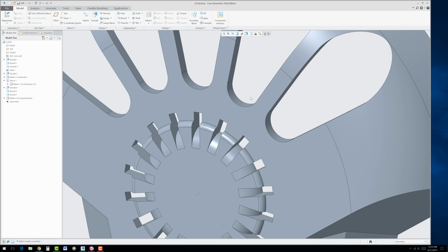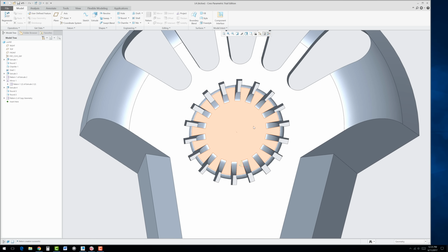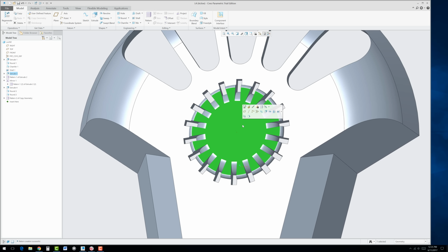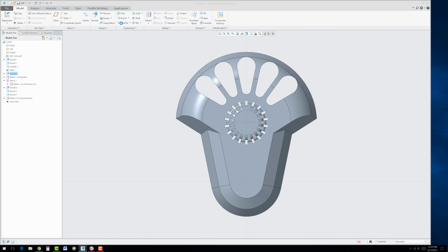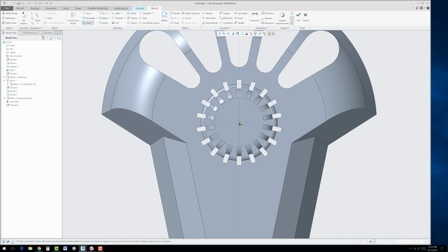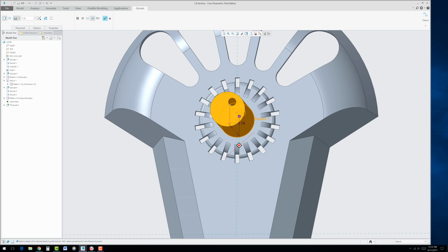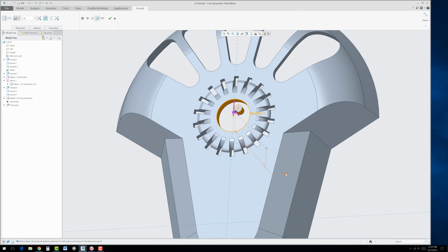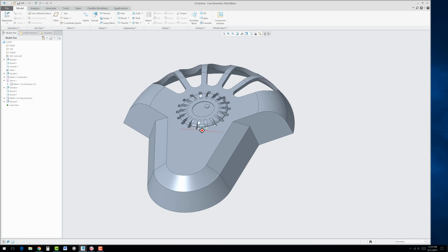Okay. Now there's a little geometry in here. I didn't put any dimensions down. The print's just too small for it. But if you wanted to put that little logo in here, you could select that face. It's nothing more than a little extrusion, and it's not meant to be really anything. You just snap that in there. And then I think I have little offsets, kind of like a moon in front of a planet. Okay, hit OK, flip the direction, and just set it to 0.01 for the depth. You do not have to do that if you don't want to.